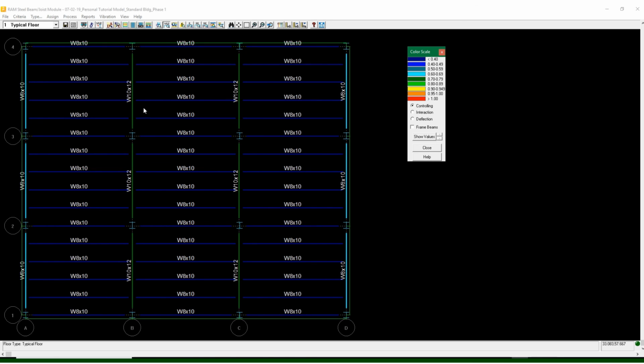The interiors that carry more load probably will be stressed out more than the ones on the perimeter. And the ones on the perimeters that are girders will be more stressed out than the infills, all right? That's carrying only floor slab directly.